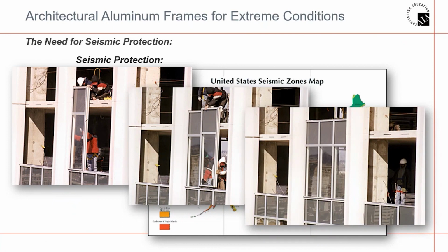It's a two-piece vertical that interconnects at the job site when the modules are snapped together, so it allows the two halves of the vertical to slide past each other as the mullion starts racking back and forth. Then each module is hung resting on top of the one below it, allowing for vertical deflection. So in a seismic area, unitized curtain walls are again very, very popular.